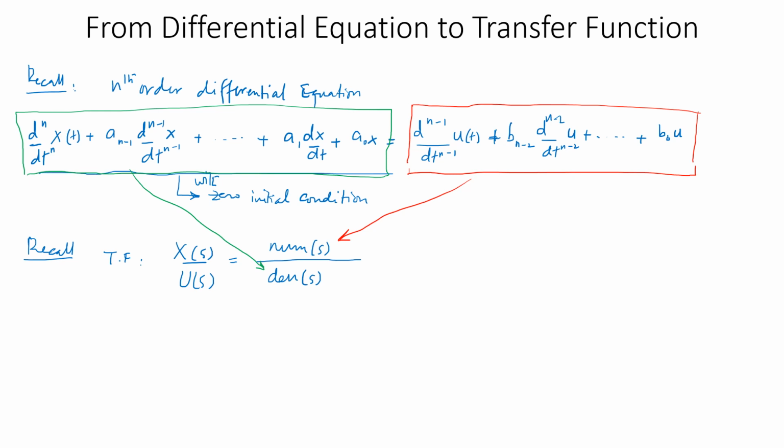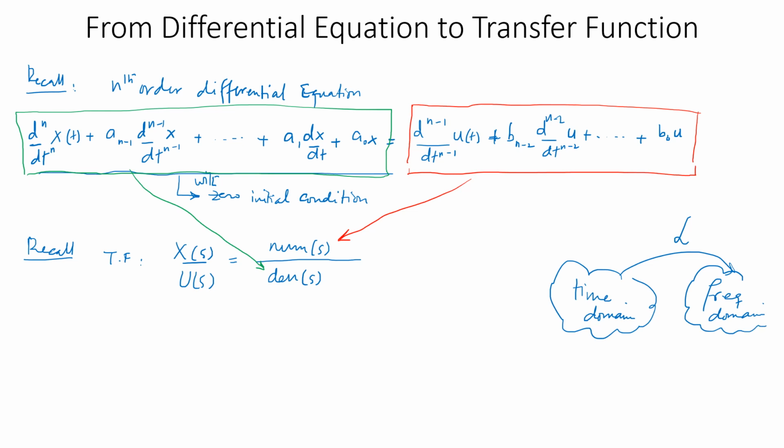And I'll ask you to consider this transformation, that all the times we have considered this S domain to be achieved when you have the Laplace transformation taken, and that was something like the time domain transformed into the frequency domain when you took the Laplace transformation of the expressions. So these Laplace transformations are going to change the time domain expressions, which are differential equations, into algebraic equations that you can very easily manage. For that reason, this side is time dependent, and this is going to be dependent on S, which is the complex variable. So let me write that one down. It is the complex variable.